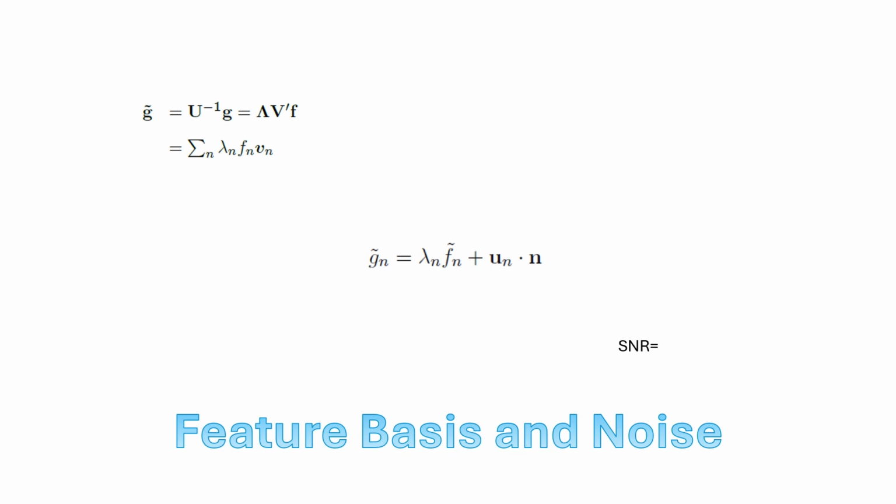Basically the signal to noise ratio we get in reconstruction is going to be proportional to the magnitude of the singular value for that coefficient divided by the noise. So lambda n is getting smaller as the index increases, but the noise is not likely to be getting smaller. The noise may be uncorrelated to the underlying structure of the signal. So what this means is that if we look back to where we had lambda n falling to 0 for the undersampled system, those higher order coefficients are unmeasurable, and the amount of information we get from the system is reduced.